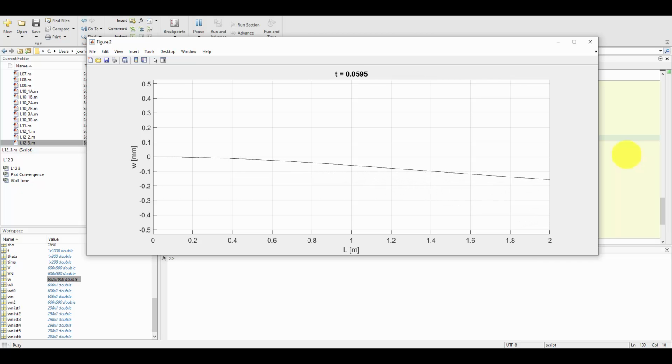When there's a point mass on the beam, then it is going to typically be fair to treat it like a 1 degree of freedom system, because that point mass is usually going to be so concentrated at one point in the beam that treating it as a 1 degree of freedom system is going to be fine, because these extra oscillations, these extra degrees of freedom in the beam and its natural frequencies are going to be so overpowered by the contribution from the point mass that it is barely going to make any difference if we actually accounted for the continuous nature of the beam in those problems. So it's usually fair when we have that point mass that we don't consider the continuous nature.